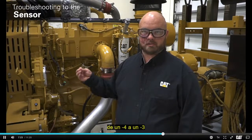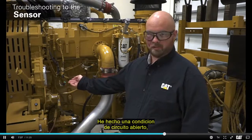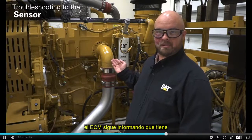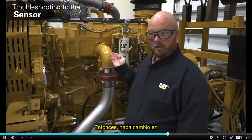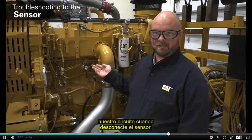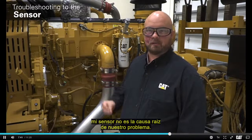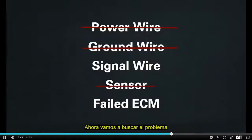and the code did not change from a -4 to a -3, well, what would that tell me about my sensor? I've made an open circuit condition, and from this point all the way back, the ECM is still reporting that it has a -4 voltage below normal. So nothing changed in our circuit when I disconnected the sensor. In that scenario, that tells me that my sensor is not the root cause of our issue. Where are we going to go next? We're down to troubleshooting the signal wire or the ECM.